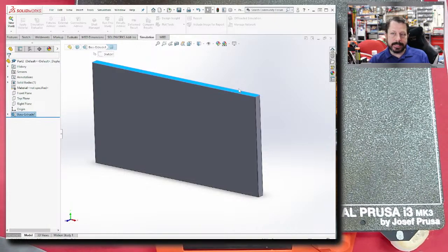The Fusion 360 one is generative: it starts with those constraints, the holes and the surface the load's on, and it grows the material between those surfaces as needed. So it ends up more spider-webby, and you can print that part directly. Now, additive fabrication and generative design or topology optimization don't make as much sense when we're talking about FDM, so the plastic printing.